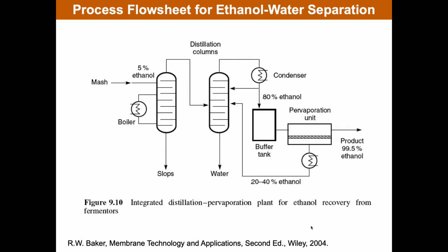The problem is, and a frontier area for membrane science in this area, it turns out that high temperature ethanol water mixtures are not suitable for all polymers, and certainly not suitable for a lot of the components like epoxies that are used in modules that are used to put membranes together. And there's been a number of failures at rather large scale in this industry. And so today, most of these units are molecular sieve units.